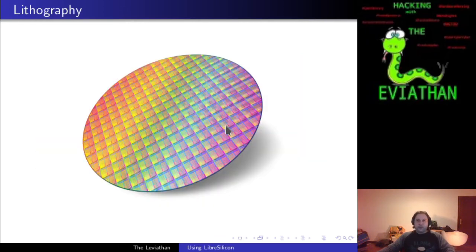The stepper aligner then takes those patterns from those masks and scales them down in size and repeatedly exposes the same pattern onto the wafer, one next to each other. The result is this tile pattern you see on this wafer. This is the same pattern exposed over and over again by the stepper.